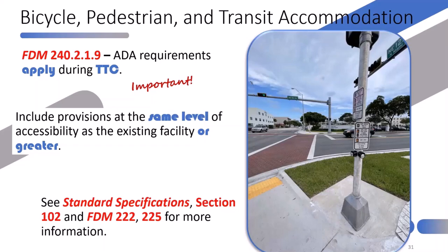And I put that stipulation, not necessarily required, on it because, again, using engineering judgment, if there is an obvious pedestrian presence because of goat trails or other indications within the project limits, then that's something that at least needs to be considered for accommodations. If there's indication that pedestrians are using that roadway shoulder, if you will, but there's no designated pedestrian sidewalk there, we still have an obligation to provide for that mode of travel, even though there wasn't an existing facility.